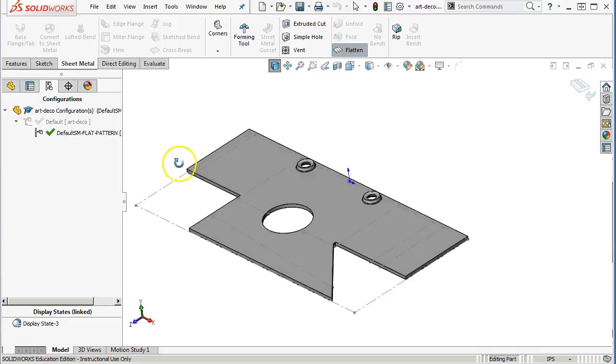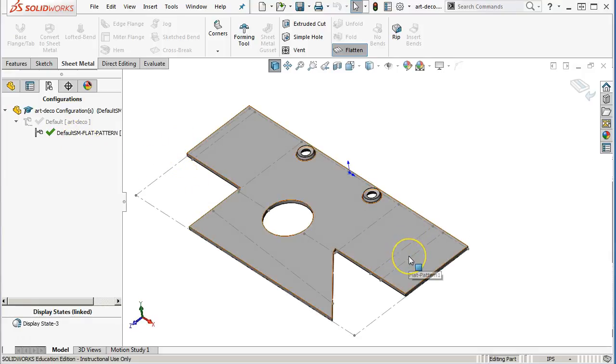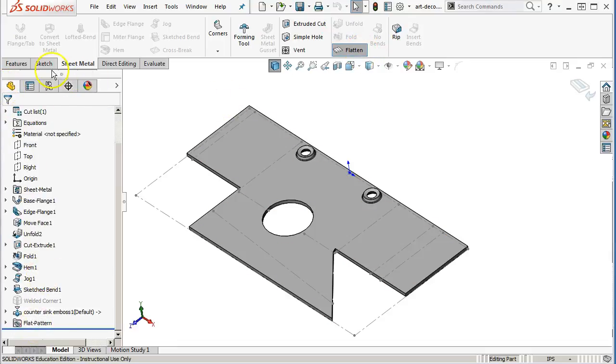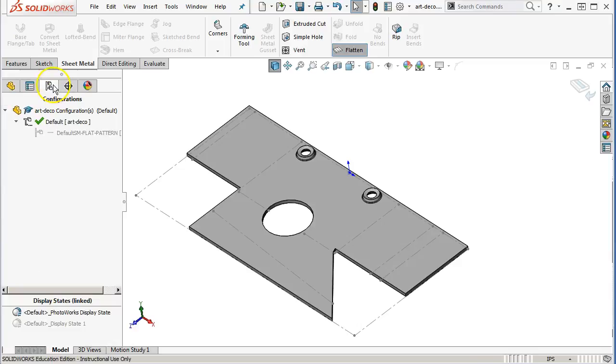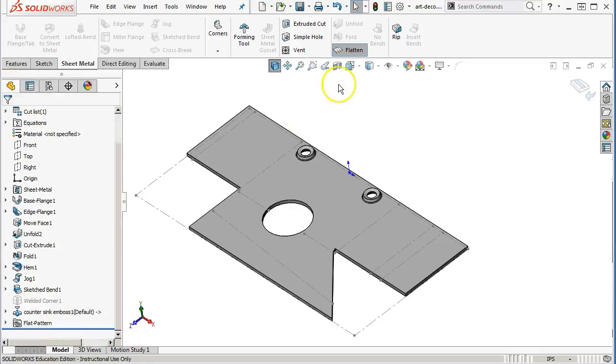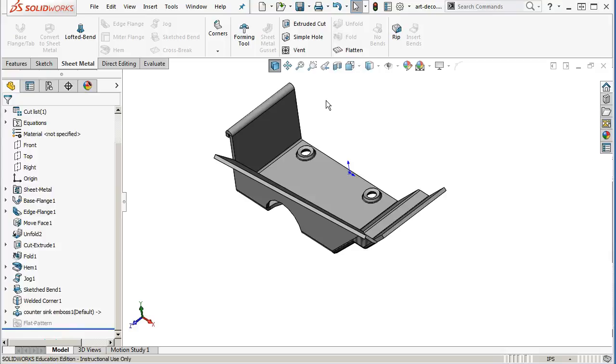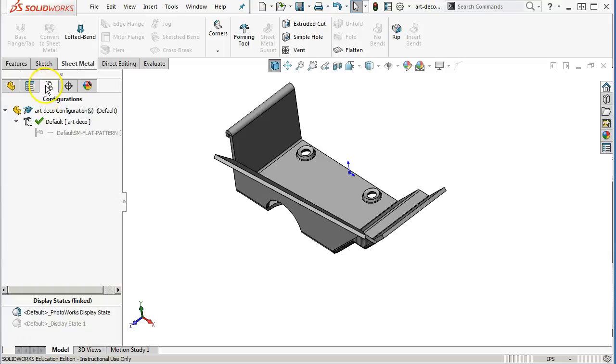And to me, this is what I want to see because this is what's going into the drawing. If there's an issue, if there are downstream errors, this is where I'm going to check. Flattening, it goes ahead and it does the flatten. It does pretty much the same thing. But once I have this derived configuration, if I flatten that, it doesn't necessarily jump over to what the drawing is reading. So I'm not sure what prompted that change in technique or strategy, getting the information over to the drawing. But out of the two, I probably don't use this near as much as I go into the configuration and pick that drive configuration. So check it out, see what you think, and we'll kind of go from there.